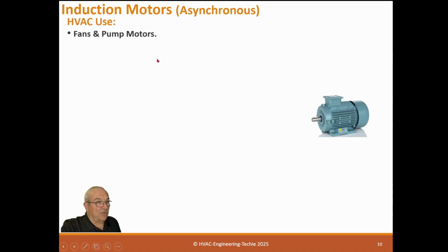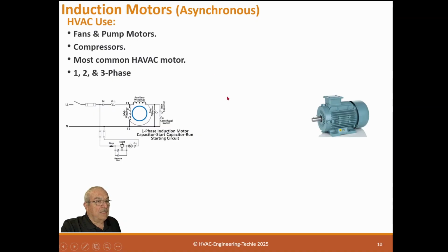We have these everywhere. Fan and pump motors, compressors, most common HVAC motors, induction motors. Single phase, 2-phase, and 3-phase motors. Starting circuit for single phase: most of them are either capacitor start or capacitor start and run.